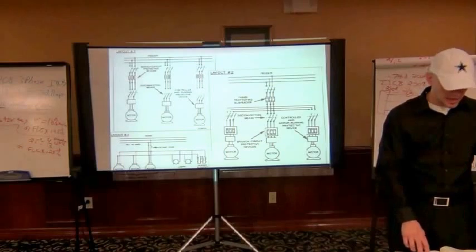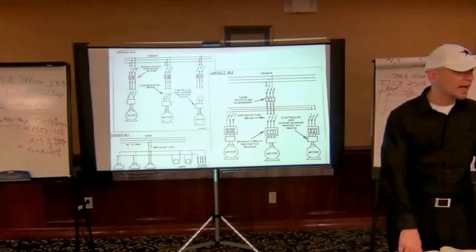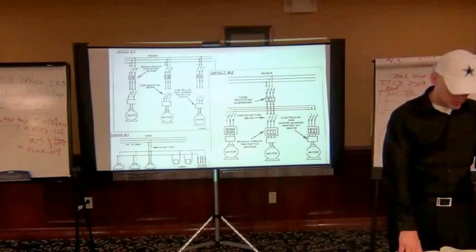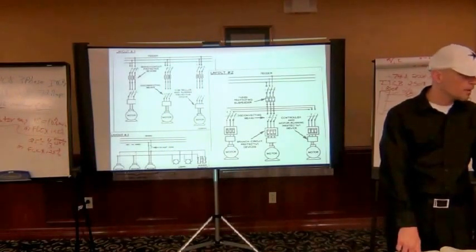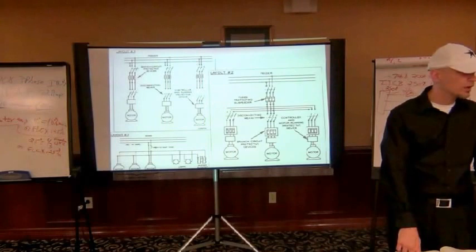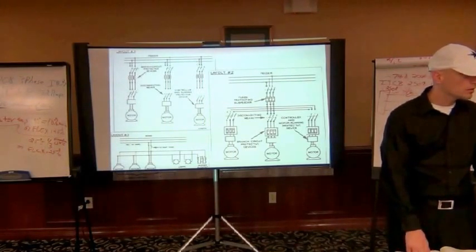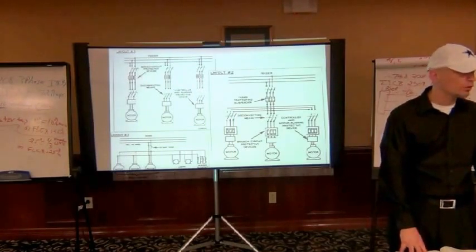Design B, C, or D, they've already pre-calculated out your LRCs. So those three, if you had a 50 horsepower motor that's used as a fire pump, the rule on fire pumps is you want to select an overcurrent protection that can carry indefinitely this LRC. So what size would you put a 50 horsepower, 480 volt fire pump motor on?